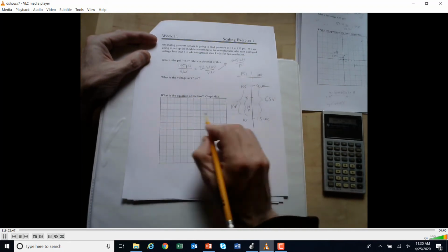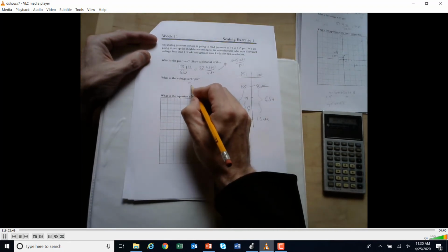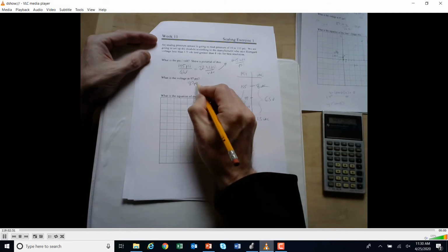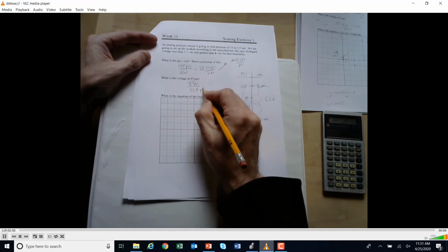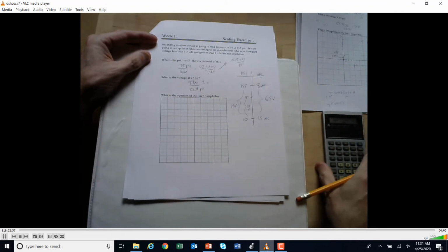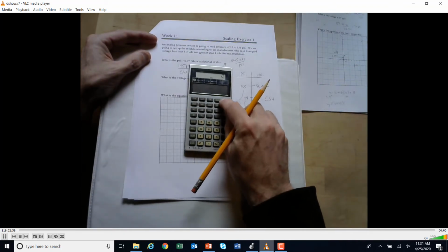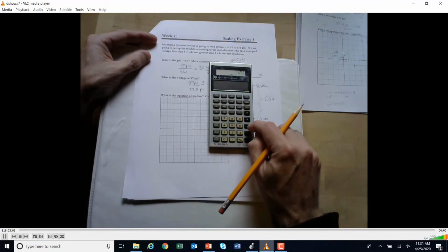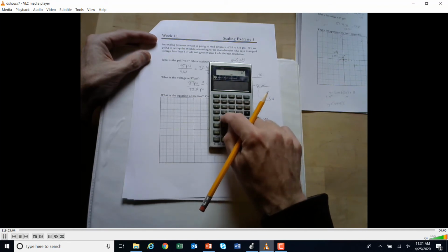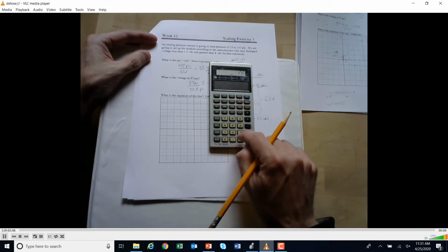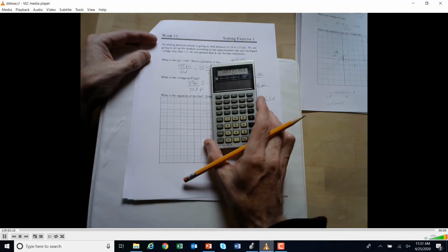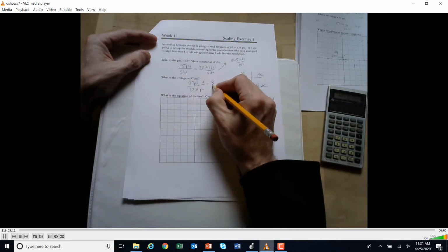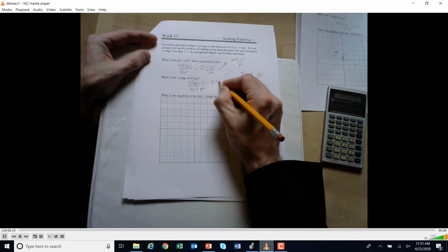So what we need to do is take how far we want to go, 87 psi, and divide it by 22.31 psi per volt. If we do that, we get 87 divided by 22.31. We get 3.899. I'm just going to go 3.9. 3.9 volts. Okay. What does that mean?